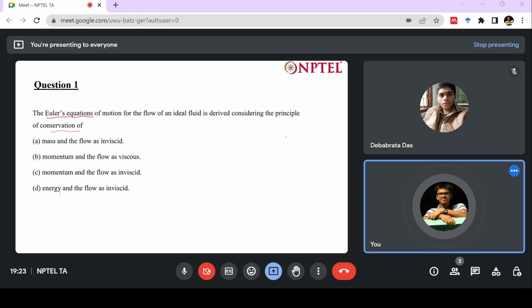So basically, what we have learned so far in the fluid mechanics course is how we interpret fluids and the different systems of interpretation. Mainly, we have learned about the Eulerian and Lagrangian frameworks, and that the Eulerian framework is more useful for observing fluid phenomena, as we stick to a particular geometric location.